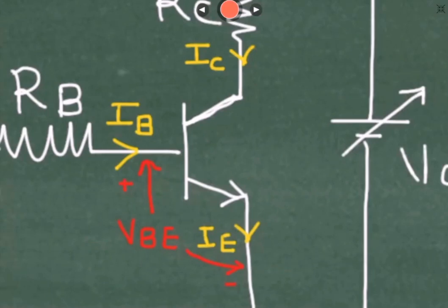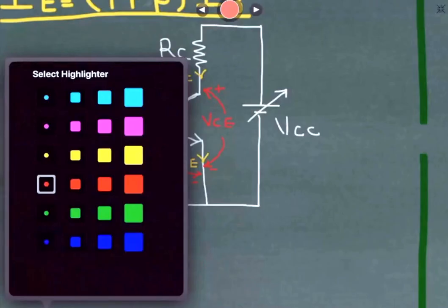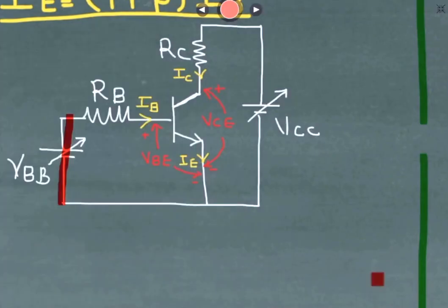Similarly over here, the voltage between collector and emitter can be denoted by symbol VCE, and this is the voltage taken between collector and emitter, with collector as positive and emitter as negative. See how I am going to write down the equation. From this point to this point, I hope you are understanding. Then I will move like this up to the base terminal.